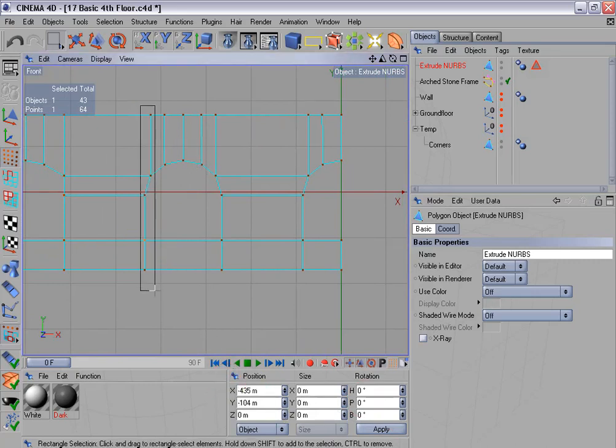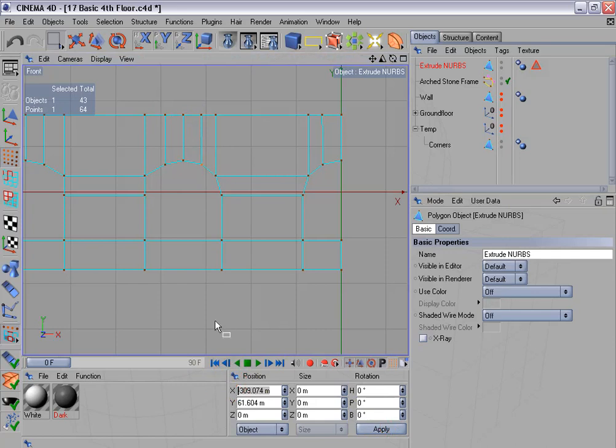And just do the same thing for this window here. And again here I'm only going to copy the X position, select this point, paste the X position, repeat this step here and here, and select this one as a reference, copy the X position, select the entire row, paste the X position and align these points.